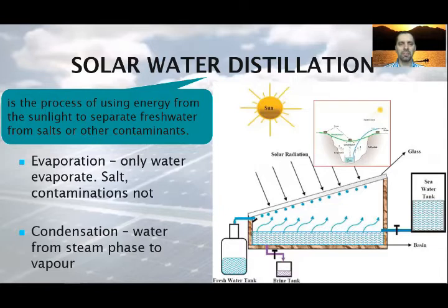The basic principles of solar water distillation are simple yet effective. As distillation replicates the way nature makes rain, the untreated water absorbs heat, slowly reaching high temperatures. The heat causes the water to evaporate, cool, and condense, leaving the salt and contaminants behind. Most solar water distillation systems, or simply stills, are black-bottomed vessels filled with water and topped with clear glass or plastic.